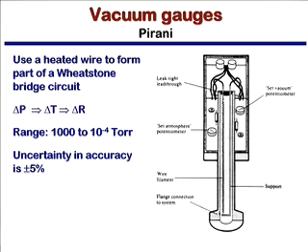And so as you have a higher and higher pressure, the temperature of that thing will change, the resistivity of that wire will change, and you simply calibrate pressure versus resistivity. You measure the changes in resistivity with a known pressure, and then when you stick it into your system, you have an ability to broadly say that as this changes a given amount of resistance, you've got a given amount of change in pressure. It is not highly accurate, but they are pretty robust, and they're the things that we use to get just a general level of vacuum.